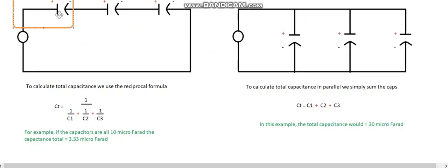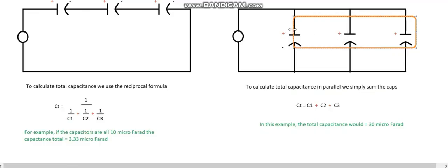It's the same as the size of this plate over here, isn't it? But where's the difference? This plate is connected to this plate, and this plate is connected to this plate. Effectively, what we've done is we've tripled the size of that positive potential plate, haven't we? We've tripled its size, so we should get a greater value of capacitance.